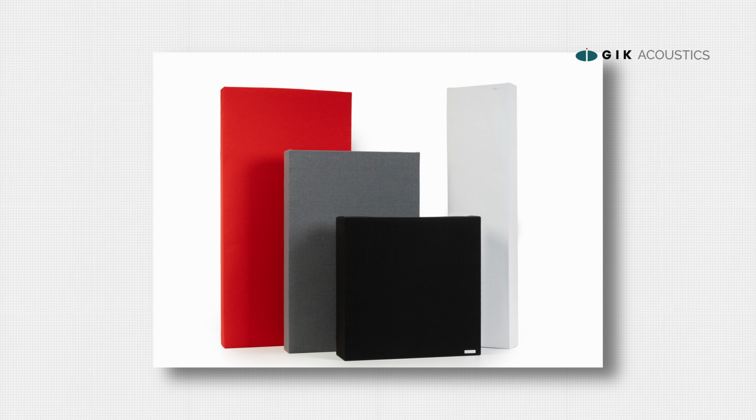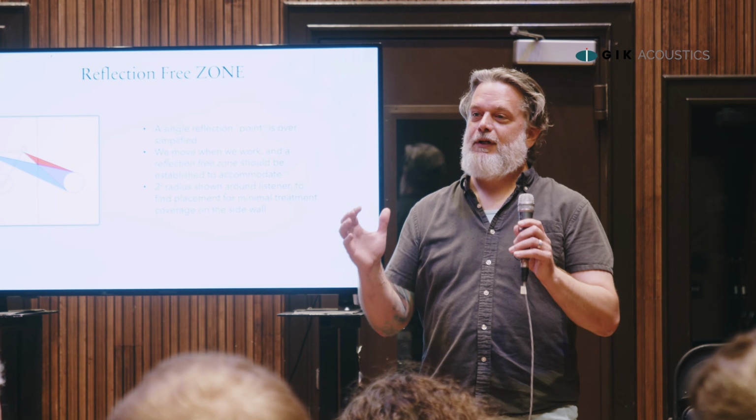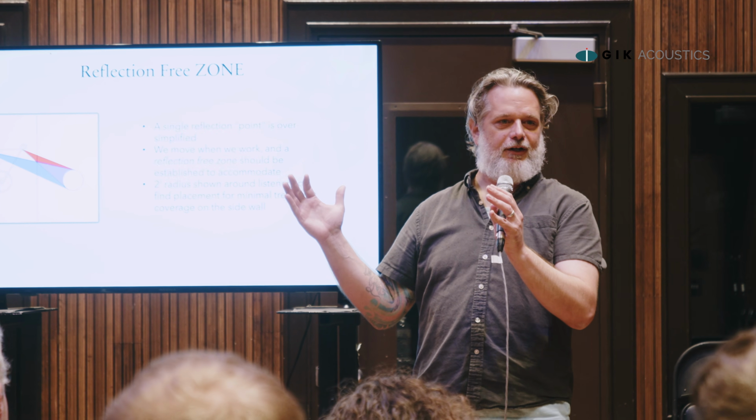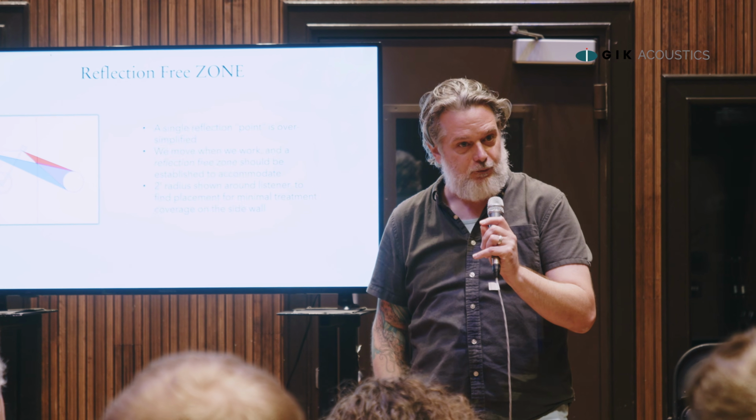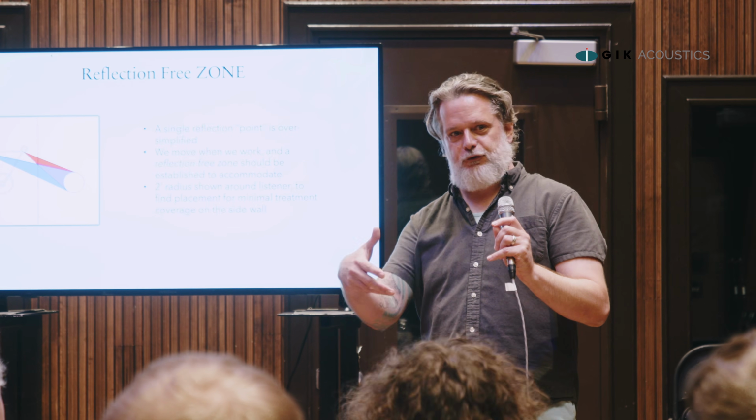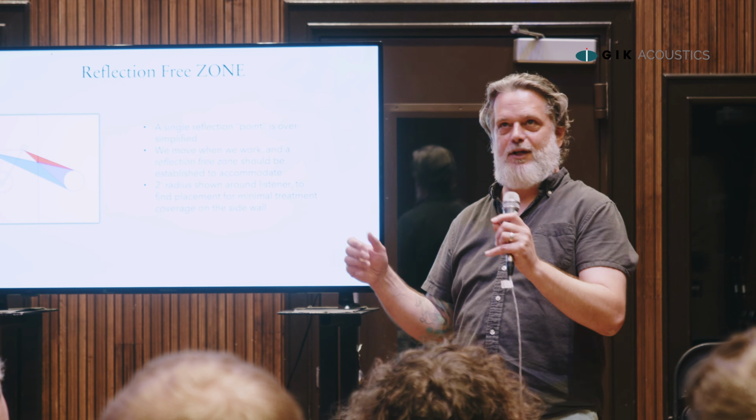But what we want to do as an acoustic designer is back up, look at the whole plan. What kind of investment are we going to make on this room, right? Say I'm going to start this plan with 244s. They're a relatively low cost per foot panel. I put a couple on the left wall, the right wall, ceiling, corners. You can grow with that, right? Later on down the road, when you get a little more coin in your pocket, take those 244s that used to be in your corner and make the sweet spot bigger.